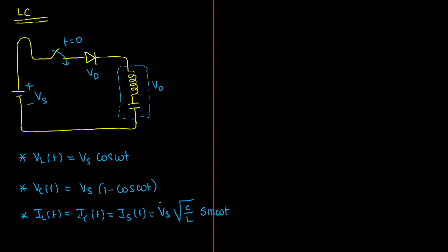Okay, so in the exam, the maximum current that can flow through the LC circuit when it is connected with the DC supply, this is the peak current we can write. This current is considered as peak, meaning maximum, don't think too much. This is called maximum current. This will be equal to supply voltage Vs into square root of C by L.